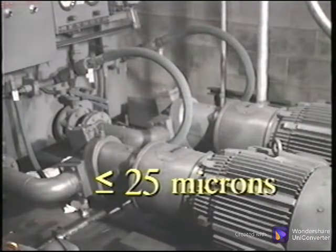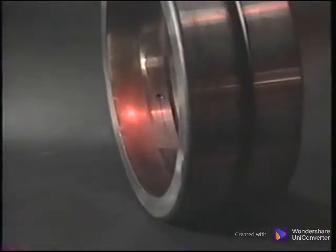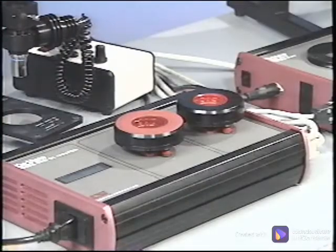Precision valves and pumps have clearances of 25 microns or less, and the thickness of the oil film in a bearing under heavy load can be less than 1 micron. Since bearing clearances can be so small, even minuscule particles in the lube can cause severe damage to the bearing surfaces. Detection of these in the oil can be performed on-site with 2 instruments.